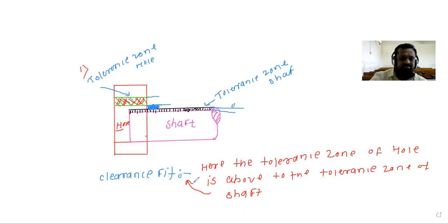Understood what is meant by the clearance fit? Clearance fit is nothing but, just observe this figure, when the tolerance zone of the hole is above the tolerance zone of the shaft. Such a condition is called the clearance fit.